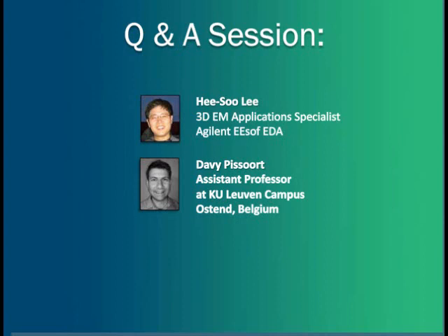A typical thing that's being said is you don't actually need a digital and an analog ground, because return currents try to return immediately underneath the actual signal. You get that separation between analog and digital automatically. So that's the main advice about different grounds. There's quite some good literature about this given by Henry Ott and also by Todd Hubing, if you want to know more about this.